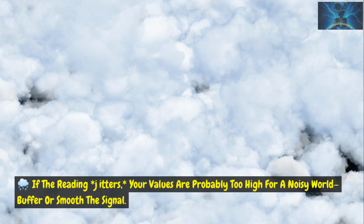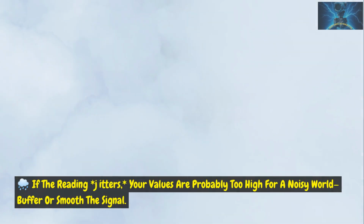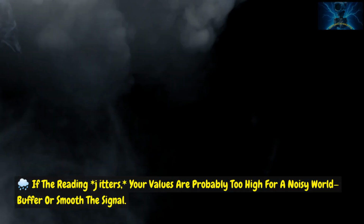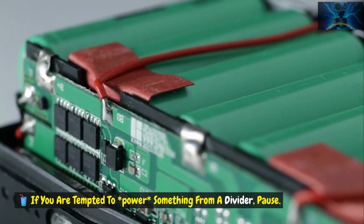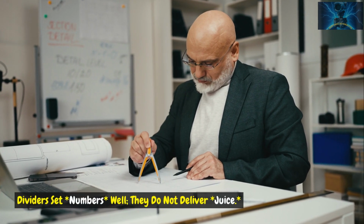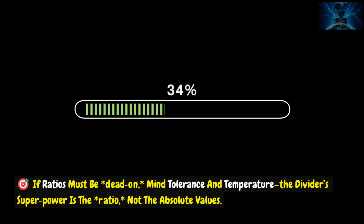If the reading jitters, your values are probably too high for a noisy world. Buffer or smooth the signal. If you are tempted to power something from a divider, pause. Dividers set numbers well, they do not deliver juice. If ratios must be dead on, mind tolerance and temperature. The divider's superpower is the ratio, not the absolute values.